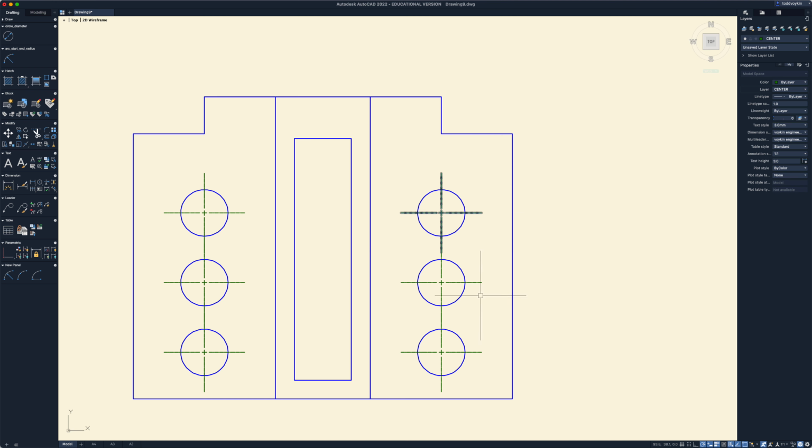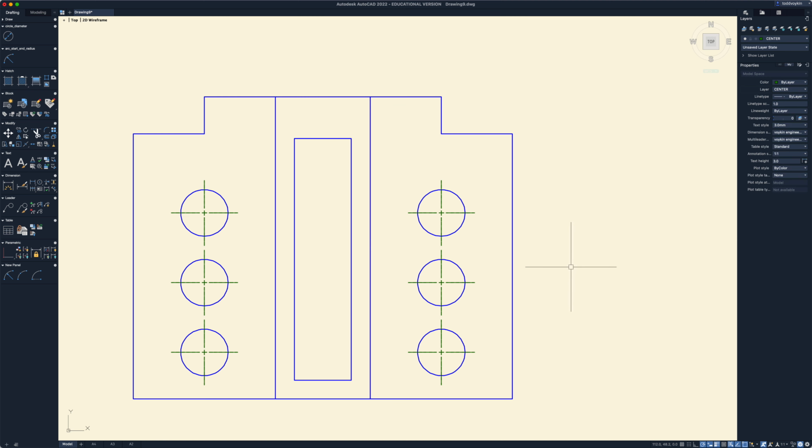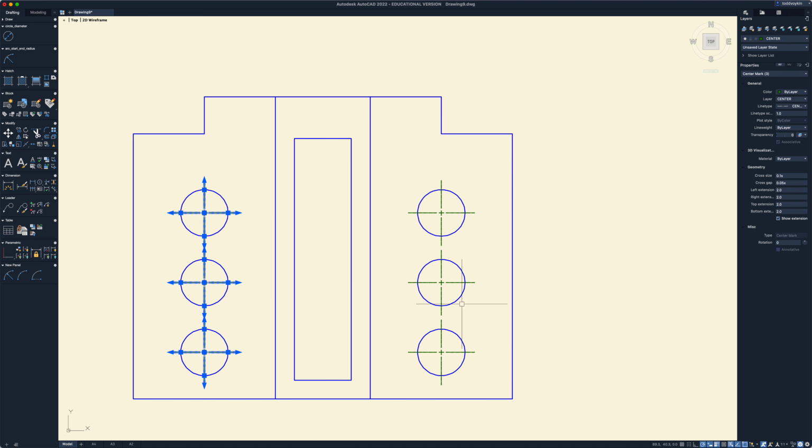So if I click on these 3 right here and these 3 right here, I'm just going to look over in the right hand side, and it says the extension is 3.5. So I'm just going to change that to 2 and see how that does. So we'll take a look at it now. Okay, that looks great. I got a slightly little space between there, and now we're just going to change the line type scale to 15 as well.